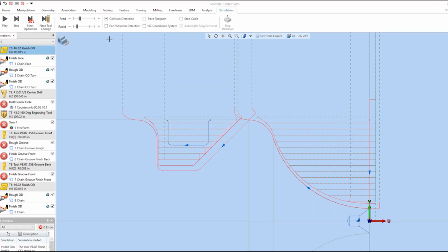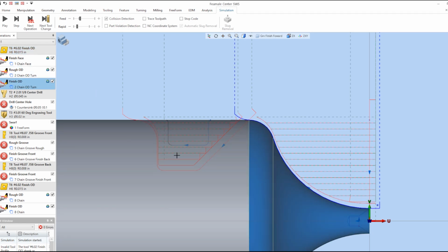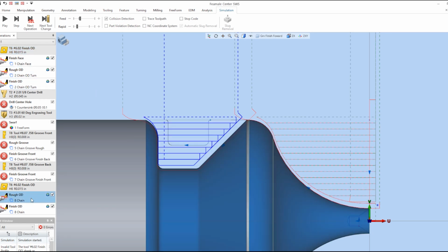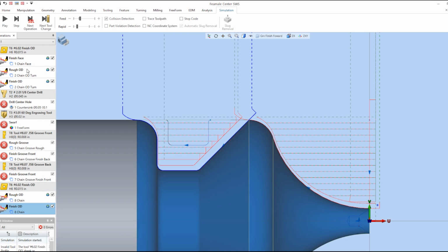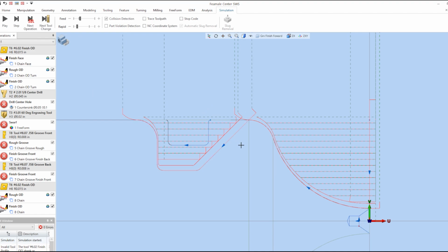All right, here we are in Esprit TNG. This is the software I use to program for the Mazak. Let's look at this roughing cycle, and this finish turning, and this roughing cycle, and so on, which are being used just to demonstrate this. This little part here is actually the dead center thing I used for that needle video I did a few videos ago, and I just added this undercut, and I also added an OD groove here which I have suppressed right now.